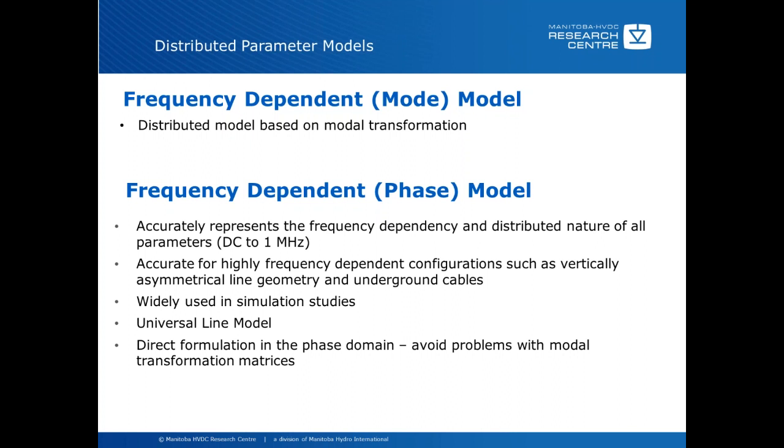Sometimes we call this the universal line model because you can model overhead lines as well as underground cables or a combination of these two. The frequency dependent phase model is directly formulated in the phase domain to avoid problems with the modal transformation matrices.